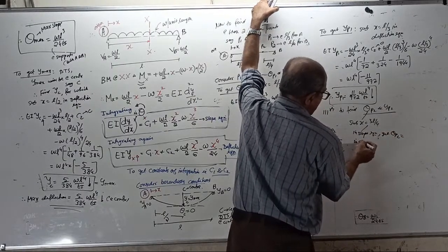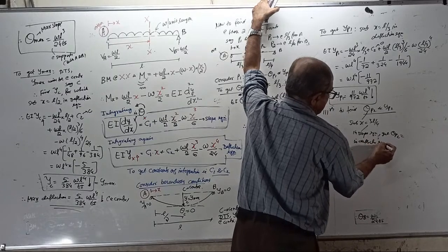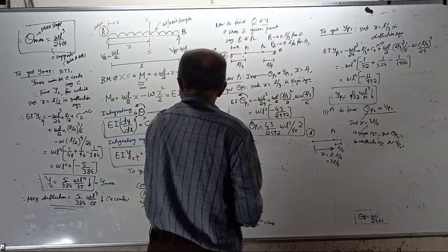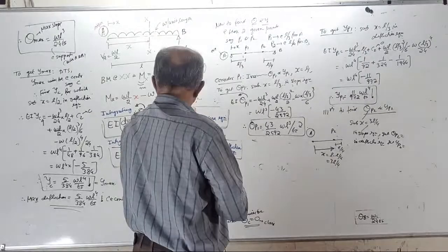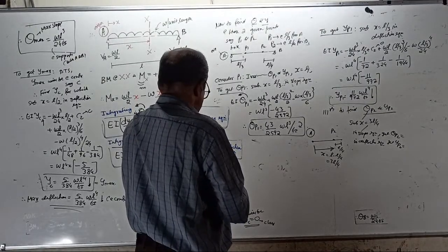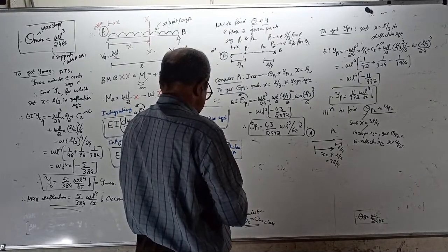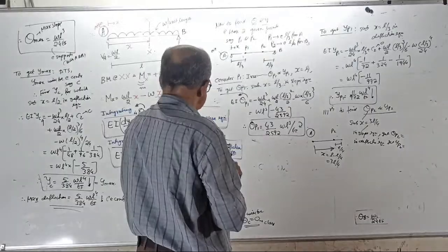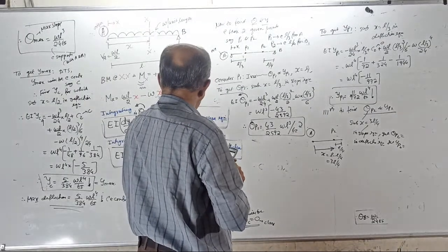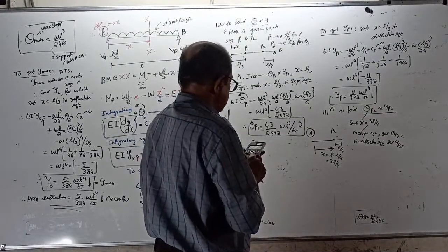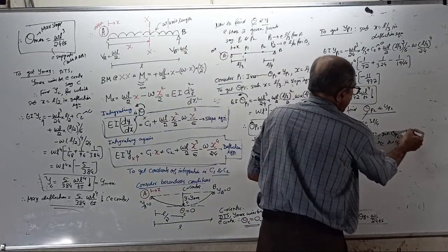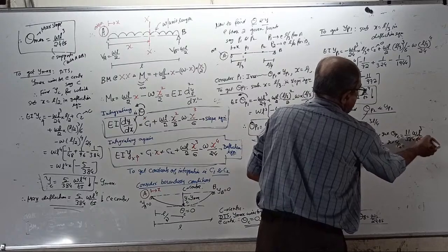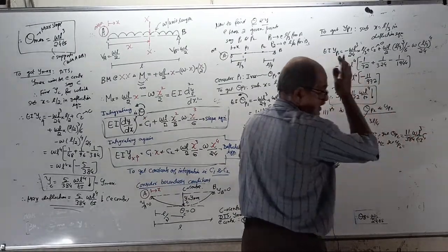And in the deflection equation, get y P2. I will directly give the answer to you. Check the answer. Slope: minus 1 by 24 plus 1 by 2 into 1 by 16, divided by 2, minus 1 by 6 into 1 by 64. The slope answer is 11 by 384 WL cube by EI, anti-clockwise. Plus will come.